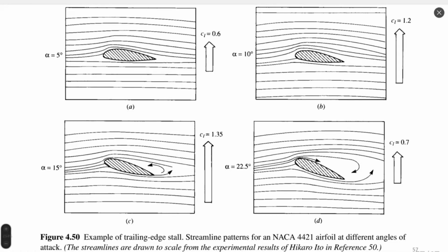Flow behavior is very similar for case A and case B. Flow patterns are smooth. Such flow can be calculated with Laplace's equation, and lift coefficient can be obtained with Laplace's equation or the numerical method we discussed last time, the source panel method, to obtain lift and flow distribution.